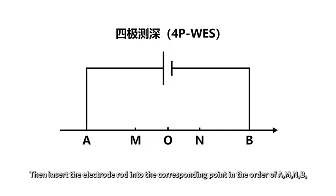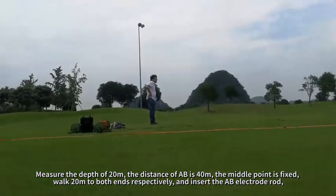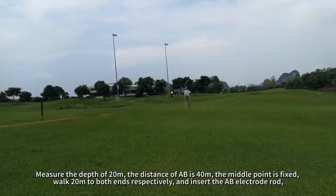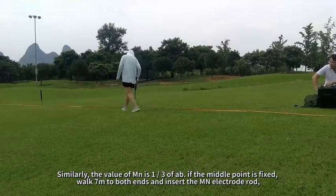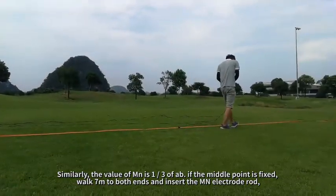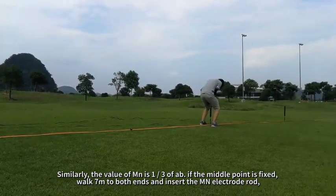Then insert the electrode rods into the corresponding points in the order of A, M and B. Measure the depth of 20 meters. The distance of AB is 40 m. The middle point is fixed. Walk 20 m to both ends respectively, and insert the AB electrode rods. Similarly, the value of MN is 1/3 of AB. The middle point is fixed. Walk 7 m to both ends and insert the MN electrode rods.